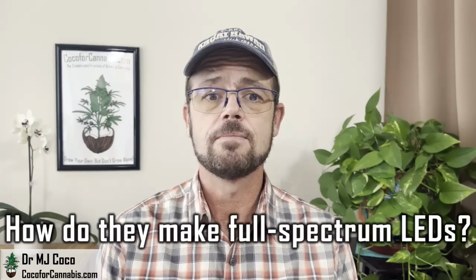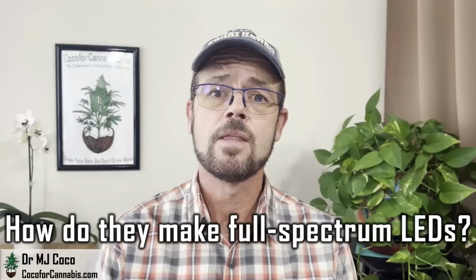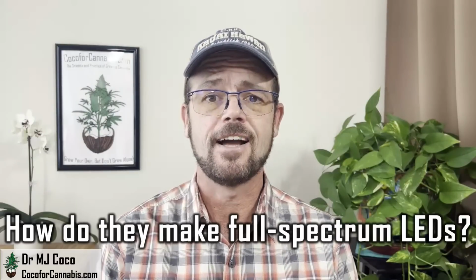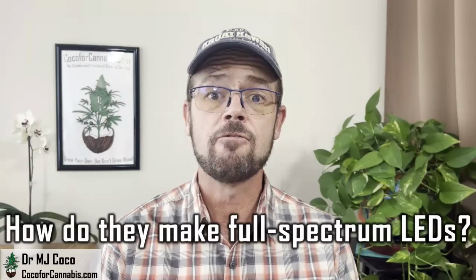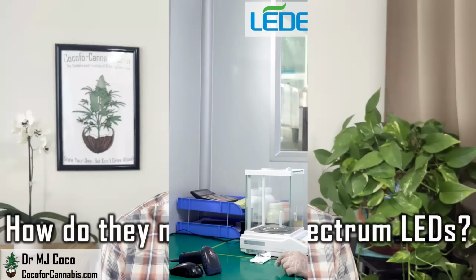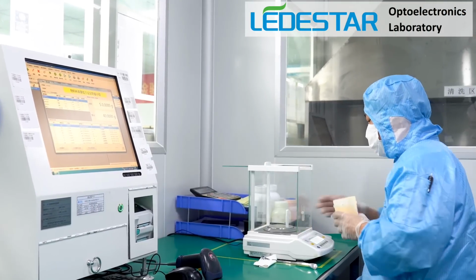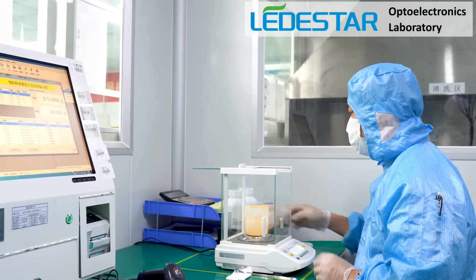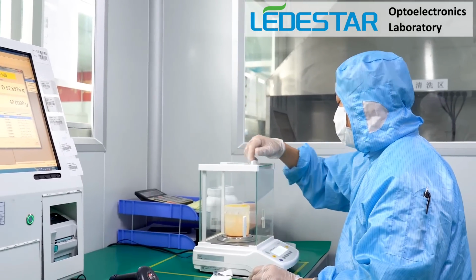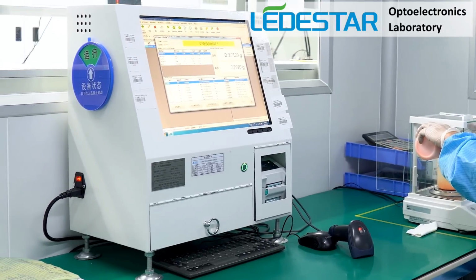There are two ways. You can embed three semiconductors in a red, green, blue set, or you can use a blue semiconductor and filter the light with yellow phosphor. The second option is how the full spectrum diodes on your grow light are made. Full spectrum diodes, like the Samsung LM301H or the Lextar 302H, use semiconductors that produce 450 to 460 nanometer light. The light that comes out of the semiconductors is blue.